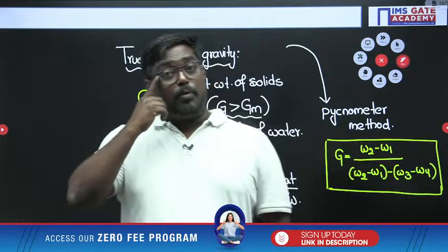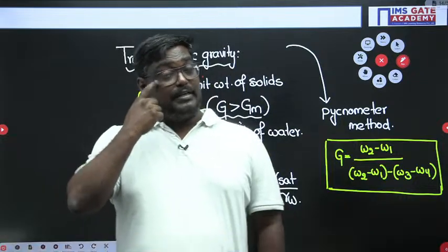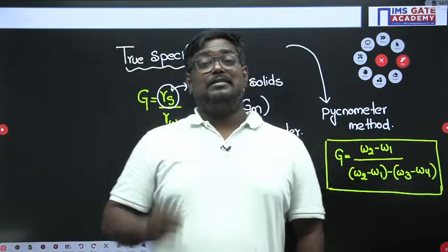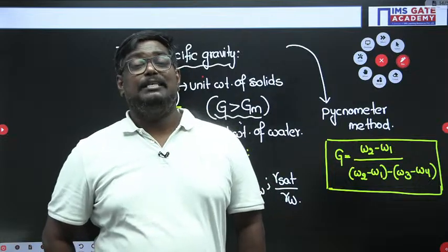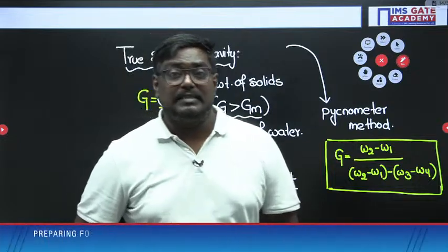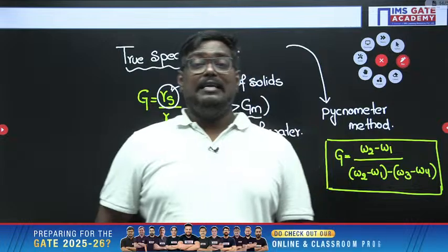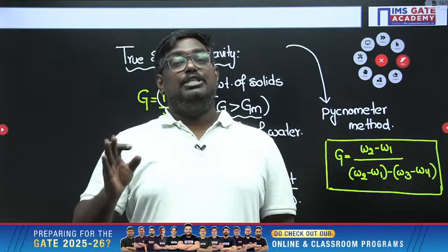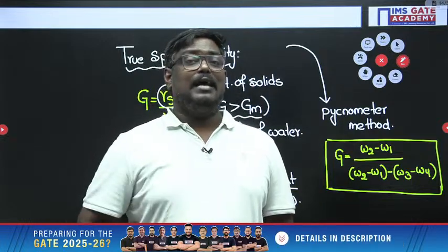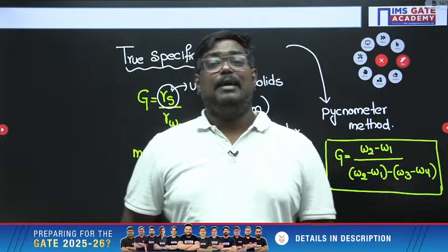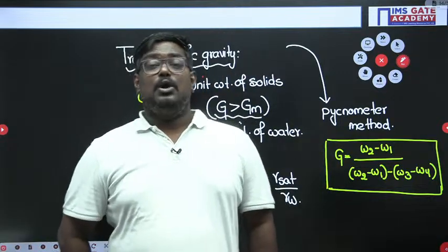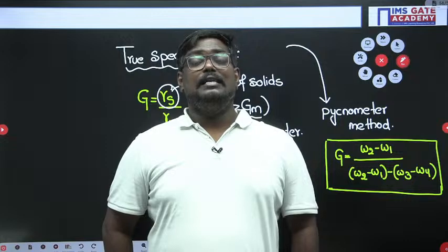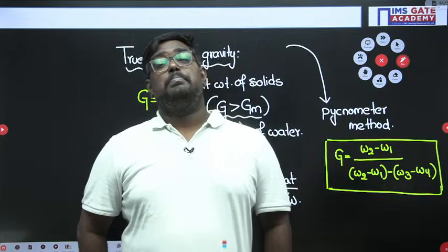And if I talk about unit weights, bulk unit weight is given as gamma is equal to gamma w into (G plus eS_r) upon (1 plus e). Similarly, gamma d is equal to gamma w G by (1 plus e). Similarly, gamma sat is gamma w into (G plus e) upon (1 plus e). And you know gamma d is equal to (1 minus na) into gamma w G by (1 plus water content into G).